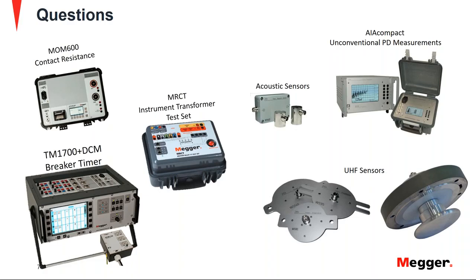So depending on the number of measurement channels you have, maybe you have both of them there. Or you have the UHF sensors, you identify you have partial discharge activity, and then you can switch to the acoustic sensors, which are something like piezoelectric sensors, because the partial discharge activity actually creates pressure waves that propagate through the GIS and can be decoupled through piezoelectric sensors and can help to identify where the partial discharge is taking